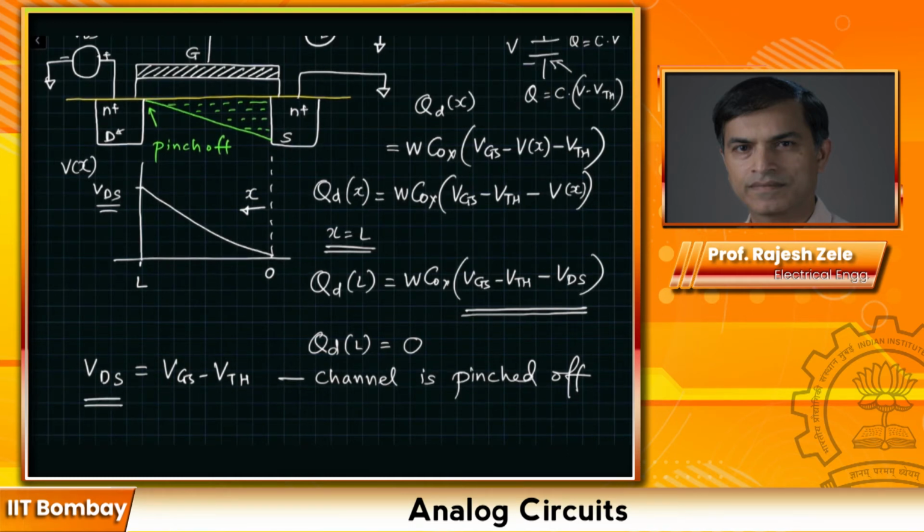You would expect that this profile would change in this fashion. Look at the yellow now. So the channel pinch off will happen slightly earlier. And this should remind you of the effect we saw in the bipolar device. In the bipolar device, when you have a base to collector junction that is reverse biased, then the width of the base reduces.